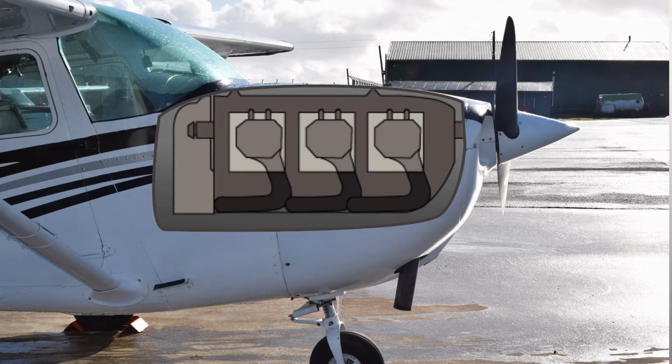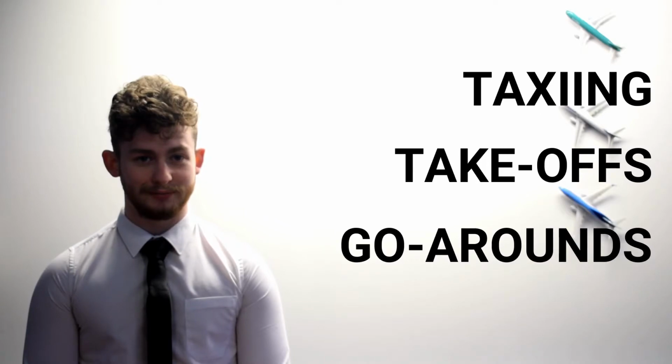Most small aircraft are air-cooled, which is accomplished by cool air flowing into the engine compartment through an inlet behind the propeller hub. This cool air is directed by baffles to the hottest part of the engine, such as the cylinder. The air is then expelled through the opening or openings in the lower aft area of the engine cavity. However, this system is less effective during high power, low airspeed operations such as taxiing, takeoffs and go-arounds. Also, high speed descents can shock cool the engine due to the excess air.